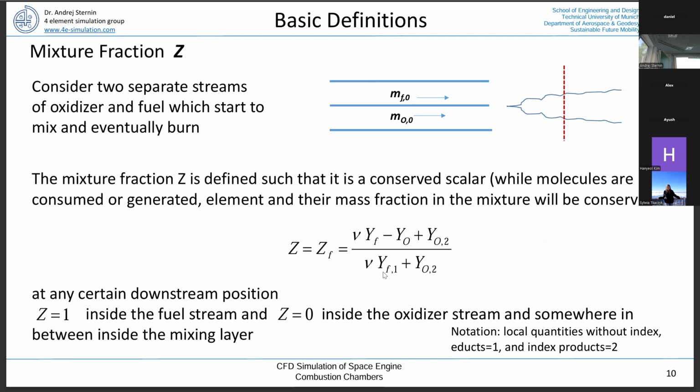Now, if we look into resolving the flame sheet, the flame thickness, we see that in the beginning of the cold side of the flame, due to the local heat release, we have a local expansion, and then we are generating turbulence on a certain length scale. Not on a large scale, but on a smaller scale, the scale of, let's say, the small eddy.